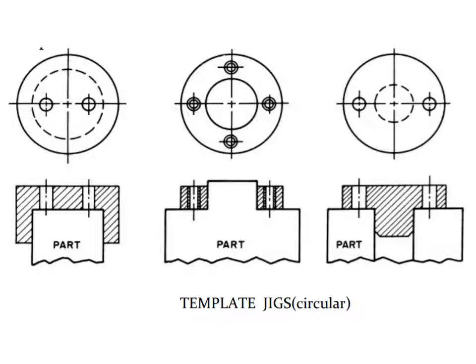So in order to avoid such complications and to get a consistently high accuracy on the hole, we have to go for using a particular fixture or a jig for the purpose of drilling this hole. Let us see how it is done.